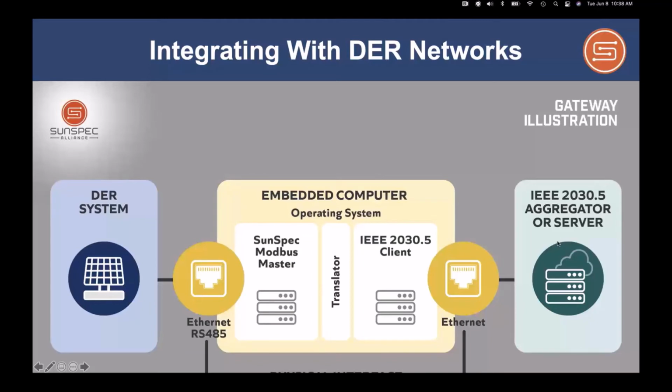Sam Yasser asked, how are utility companies implementing their end of the DERMS? For example, I'm working with a local utility company that is requiring the capability to disconnect and connect DERs and to limit maximum active power for DERs. How will they be able to issue these commands from their end to reach the DER gateway and control DERs at my project? Okay, great question, Sam. That is the subject of this IEEE 2030.5 protocol, and in fact, the whole system you see here is to enable that remote command and control.